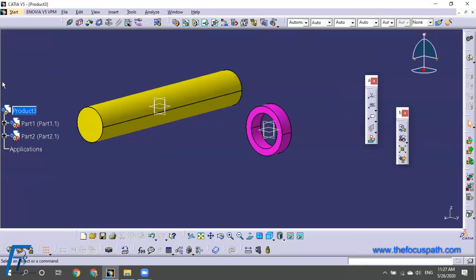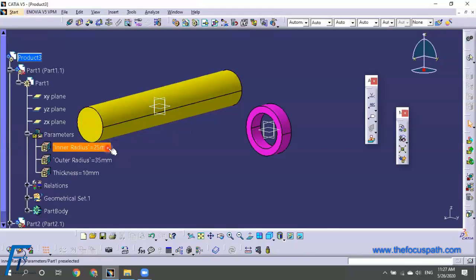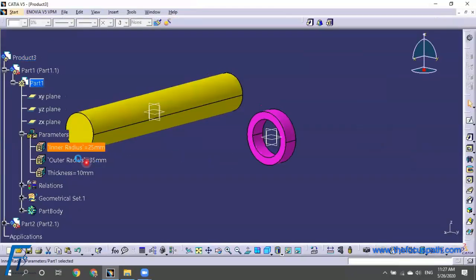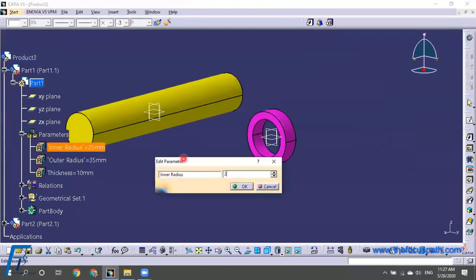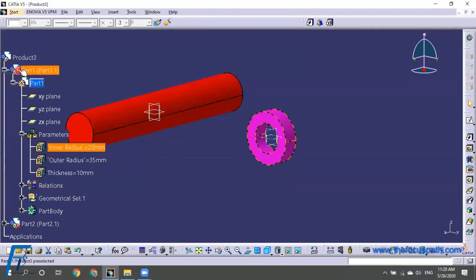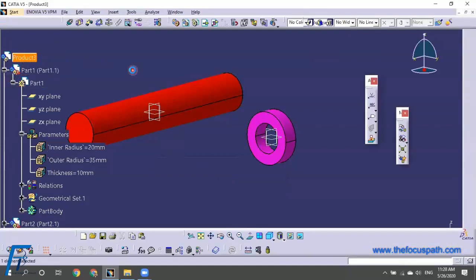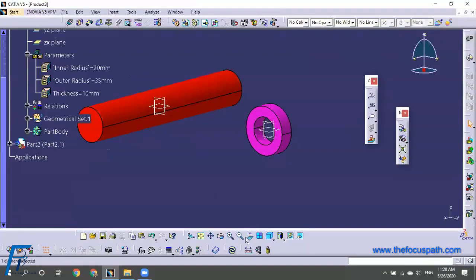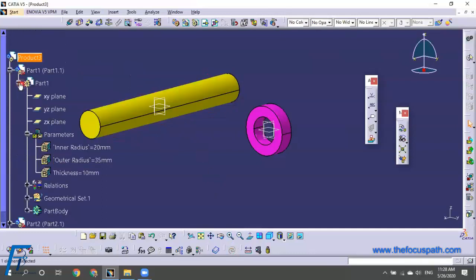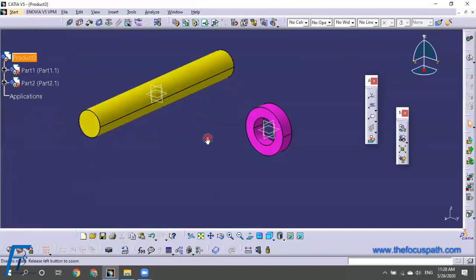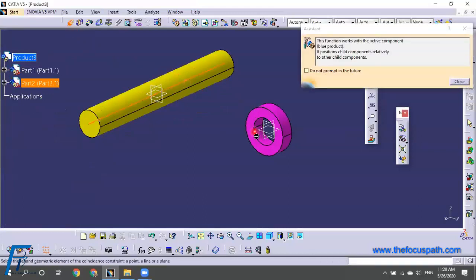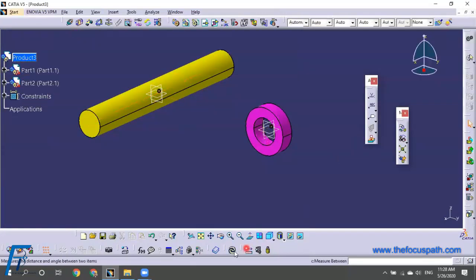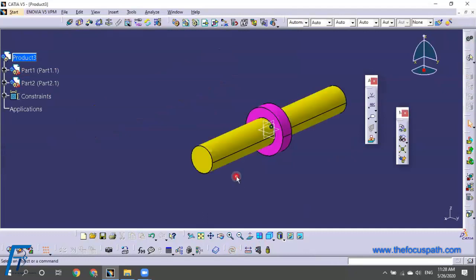When external parameters are used, only the formulas are related, only the geometries are getting changed. So if you do these changes, say for example, I'm going to change this to 20 mm. It gets changed, but it will not get aligned. So in external parameter, whatever you are going to do, it is independent of the axis, right? You have to use assembly constraints and give assembly constraints. So that means you can create this formula with assembly constraints. Any doubt so far in this case?